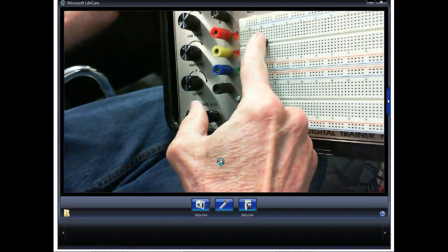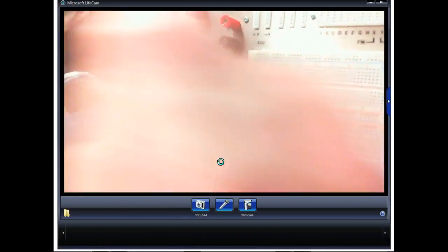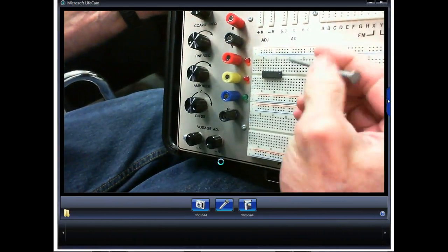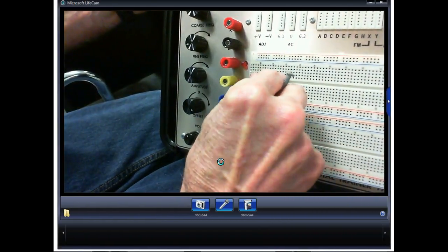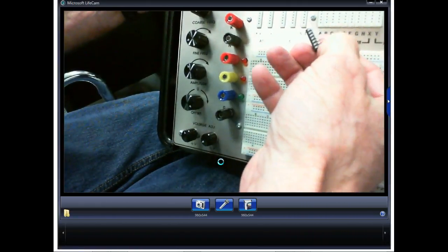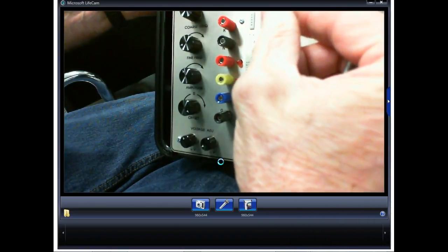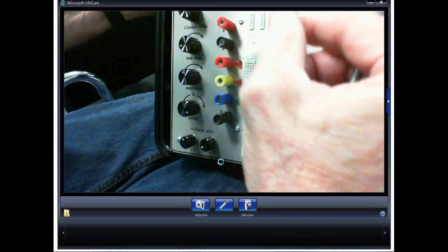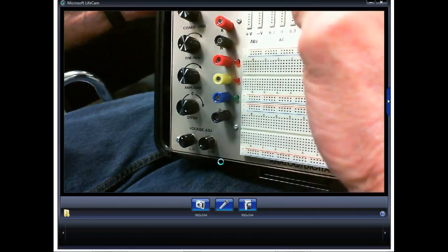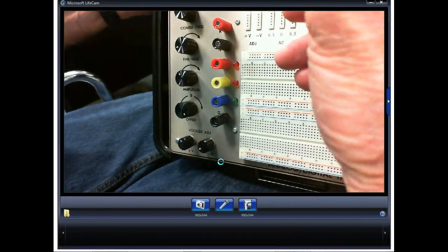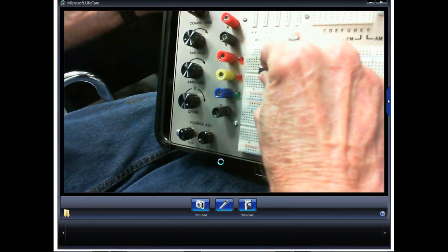Now all these holes up here belong to pin 1. All these holes up here belong to pin 2. See what I'm talking about? We call these pins for obvious reasons. By George, these suckers are sticky. So I don't want to ever come over to your desk and find these things on the table with these pins facing up. Y'all understand why? I'm not going to tell you how many of these things I pulled out of my elbow. And it's not fun for people that put them like these. So any ICs that are not being used, you need to keep them inside your parts kit.